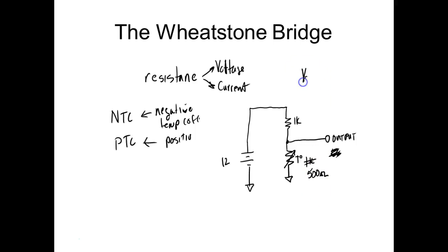We could say my voltage out would be equal to 500 ohms over 1500 ohms, and then we can multiply that times 12. And that would give me my output voltage. So this formula right here is called the voltage divider formula for a series circuit. And what we can do instead of having to calculate current. So most of the time, especially on a 2 resistor circuit, you can calculate RT in your head. You don't have to use a calculator.